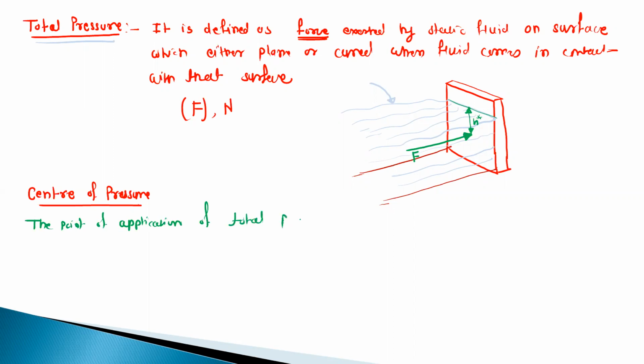Here you can see this is the free surface of the water or the fluid. With respect to this free surface, we measure the distance where the force is acting. That distance is the center of pressure, and the force is the total pressure.